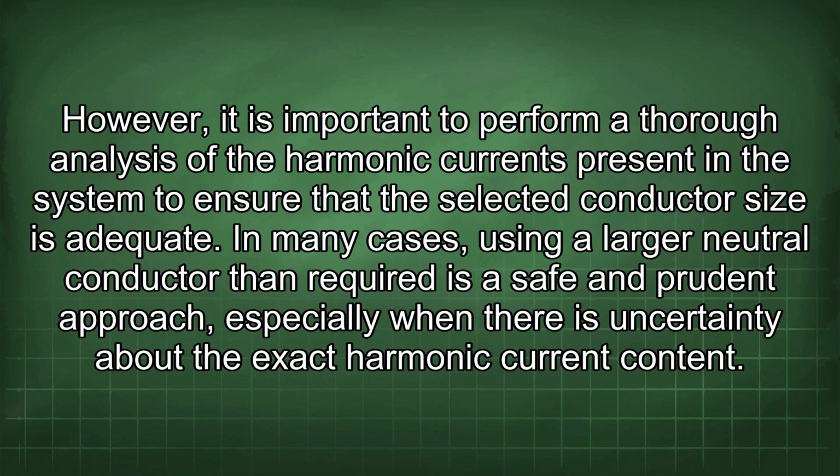However, it is important to perform a thorough analysis of the harmonic currents present in the system to ensure that the selected conductor size is adequate. In many cases, using a larger neutral conductor than required is a safe and prudent approach, especially when there is uncertainty about the exact harmonic current content.